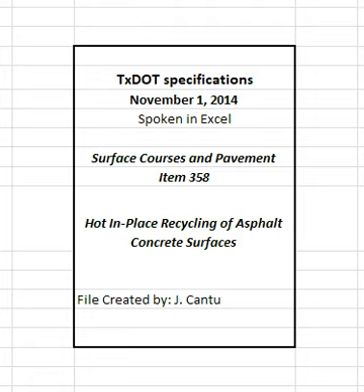1.1 Recycling. Recycling is the process in which the existing asphalt pavement is heated, softened and then milled. A recycling agent is added and the material is thoroughly mixed and placed with a standard paving screed.